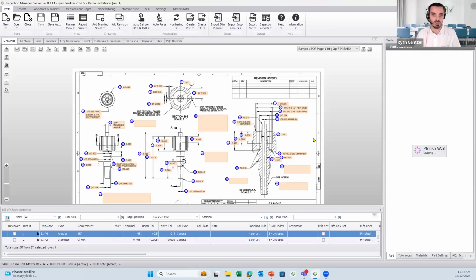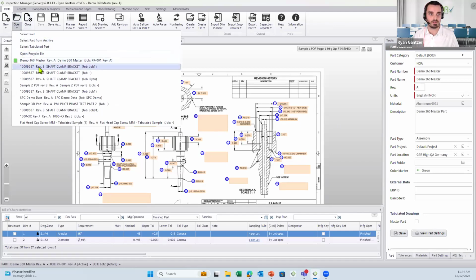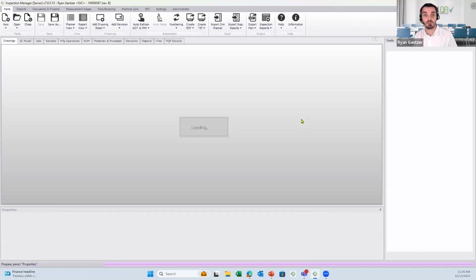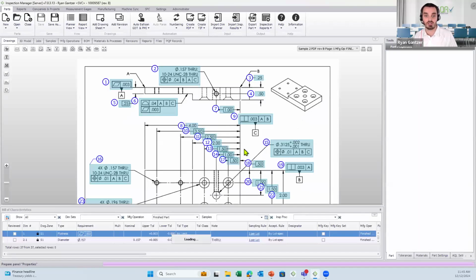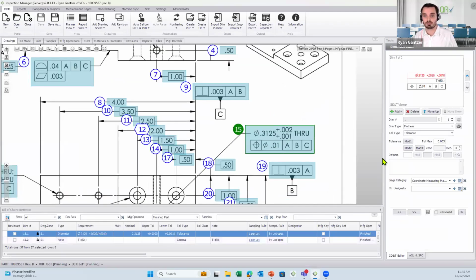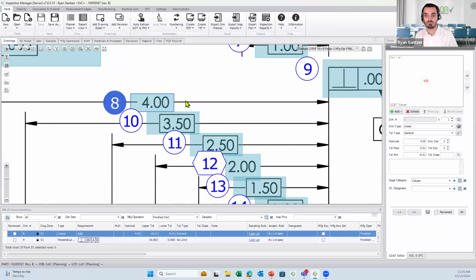Okay. Yeah. So if the dimension has the tolerance itself, let me pull that print that we were looking at most of the time today. If the print has the tolerancing on it itself, so like this plus plus, we will bring that in. If it's not on the tolerance or on the dimension, this plus or minus 10 thou, that's coming ultimately from these part categories that I keep referencing, which again is a series of defaults and preferences.